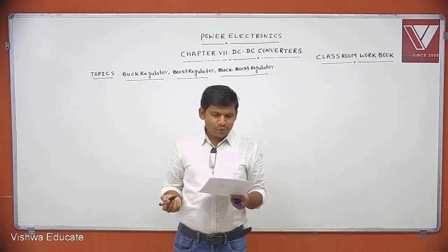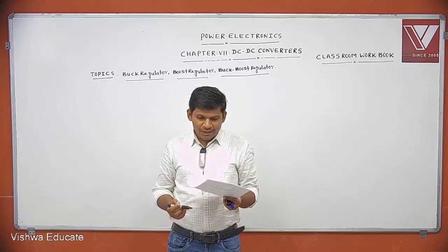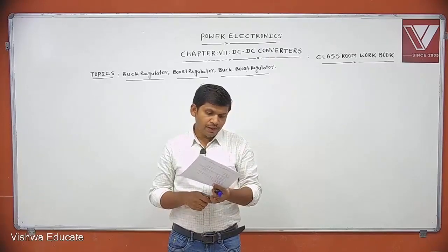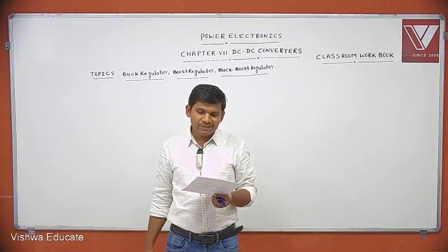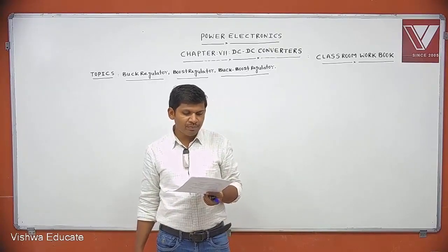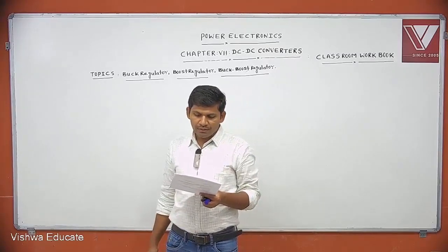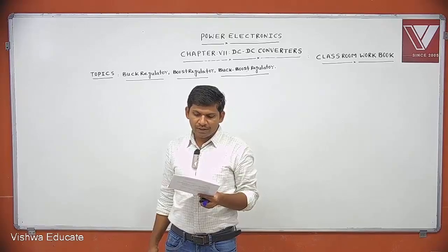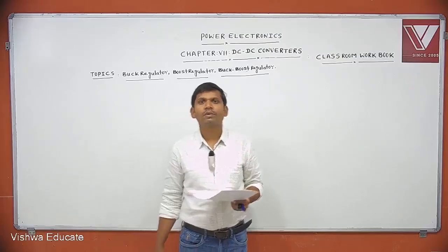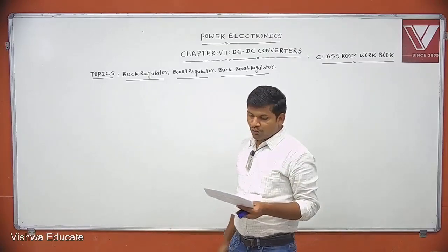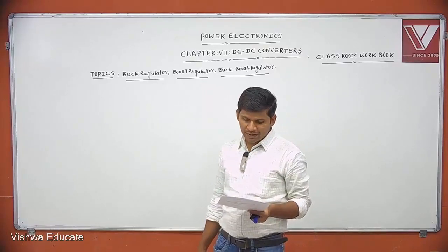In the chopper circuit shown in figure, the input DC voltage has a constant value Vs. The output voltage V0 is assumed ripple free. The switch S is operated with a switching time period T and duty ratio D. What is the value of D at the boundary of continuous and discontinuous conduction of the inductor current IL? That means you want to find the duty cycle at boundary condition.